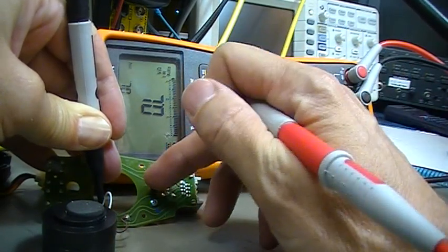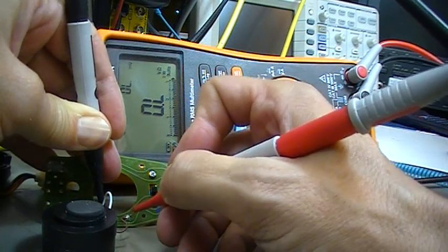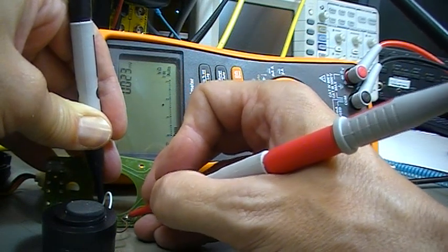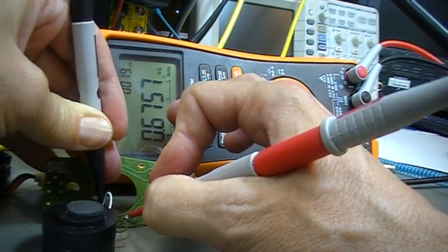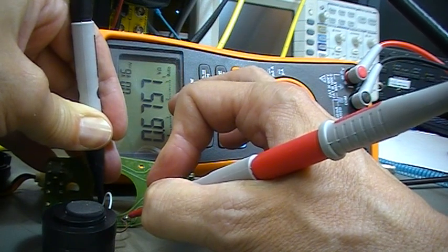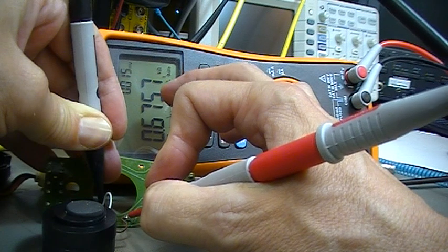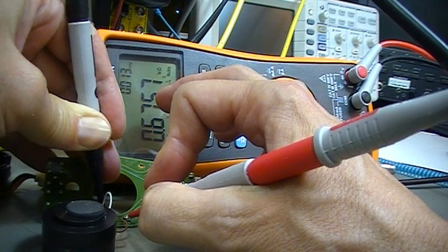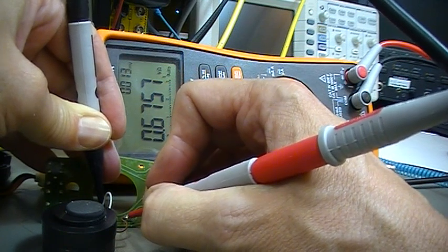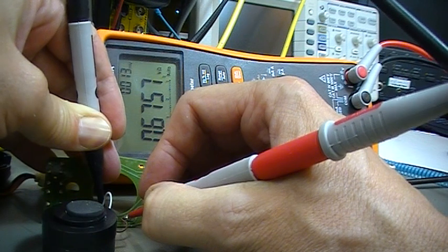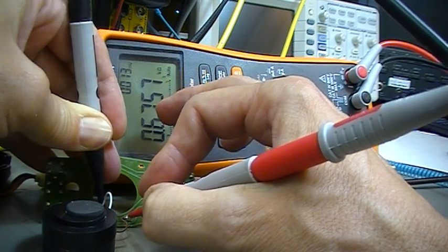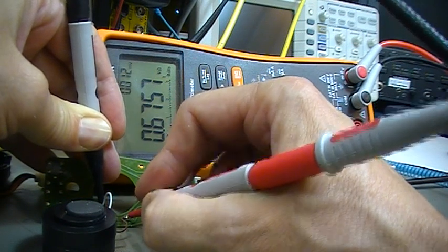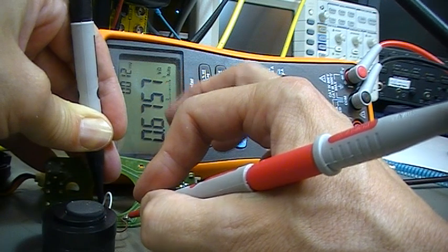When we switch this switch, again we measure this 680 ohm, which we have seen in the schematic. I already said that this is a little bit suspect to me, because two resistors in parallel must give a lower resistance together. That is what I already thought.